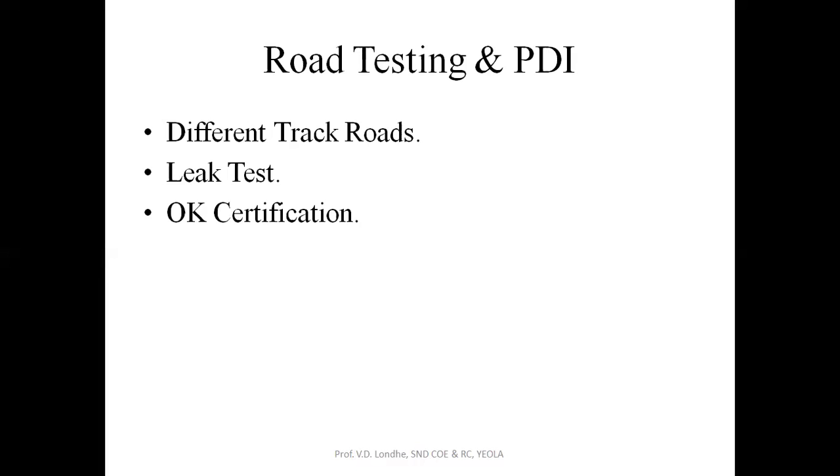In that pre-delivery inspection, the vehicle noise, then the suspension test, then any other noise coming from the gearbox or from the engine, then the vehicle stability, then the braking action, then particularly the vibration mode, meaning suspension, all these systems are certified in this PDI test. That PDI is nothing but the pre-delivery inspection test. And then after doing it, if the vehicle is confirmed, meaning there is no failure, then the OK certification tag is put on the front glass shield of the vehicle. And then the vehicle is passed and transferred to the supplier. Thank you.